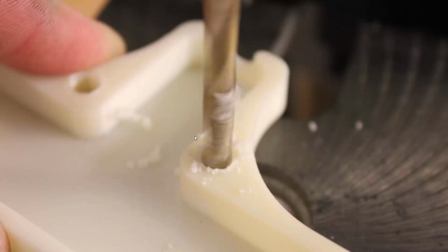All right, so here's me increasing the diameter of the holes. Going back to the idea that you never get things right the first time: some things are totally your fault, and some things are not your fault. This is my fault. I just wasn't paying attention to the size of the holes that I put in here. So when I went to insert my screws, I think they were M6 screws, they couldn't fit. Luckily, I just popped them on the drill press, widened the holes, and made note of what drill I used so I could come back into my SolidWorks file and update my CAD file to be more accurate. That's that iterative process I talked about in the beginning. If we can go through one prototype, we're going to learn from it.